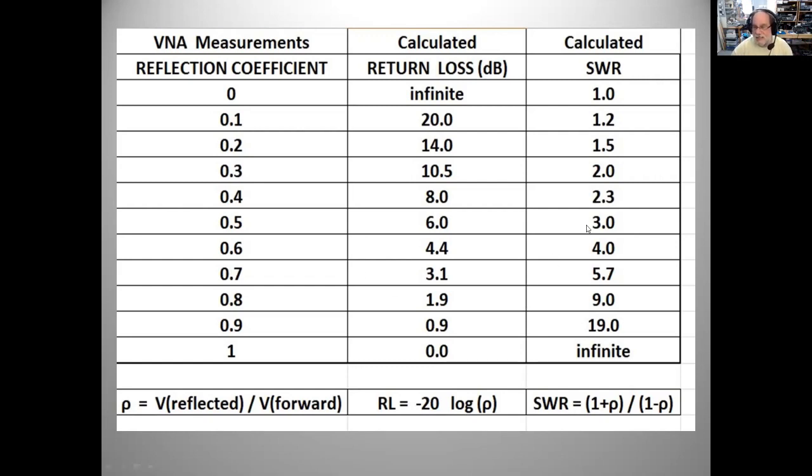That's where I start to see sometimes my radio's not happy. The radio starts to buzz or say something, and the power cuts back. So an SWR of 3, it's not awful, but it means the reflection coefficient is a half. I send 1 volt, a half a volt comes back. Well, let's see, half a volt would be what? 0.5 squared, a quarter of the power. That doesn't sound very good to me.